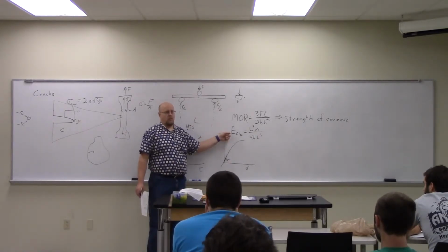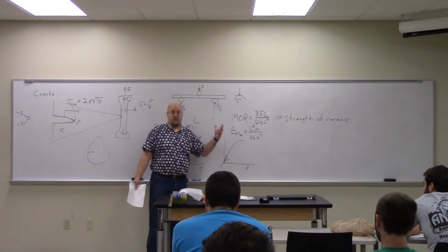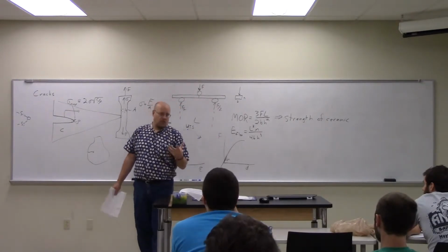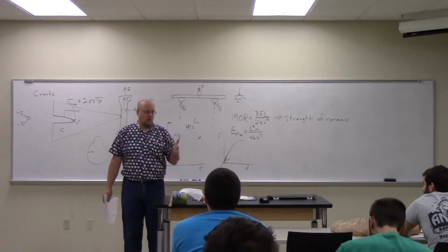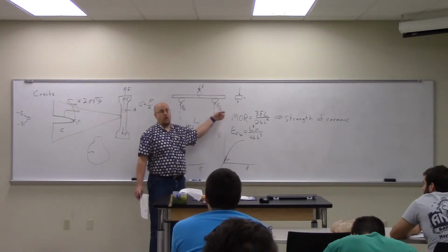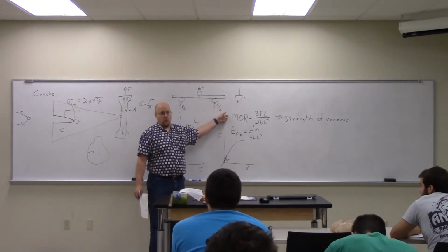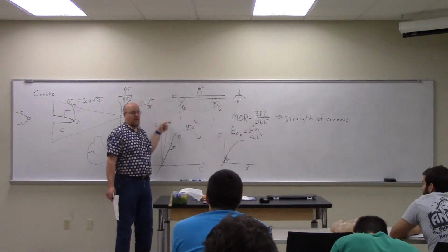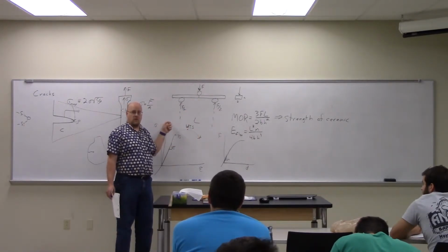You generally aren't going to just bend polymers unless it's a brittle polymer, like a piece of hard plastic that would fracture. Yeah. You might use the modulus of rupture. This is just exclusively used for brittle materials, where we're actually breaking it and where it's the breaking point that really matters to us.